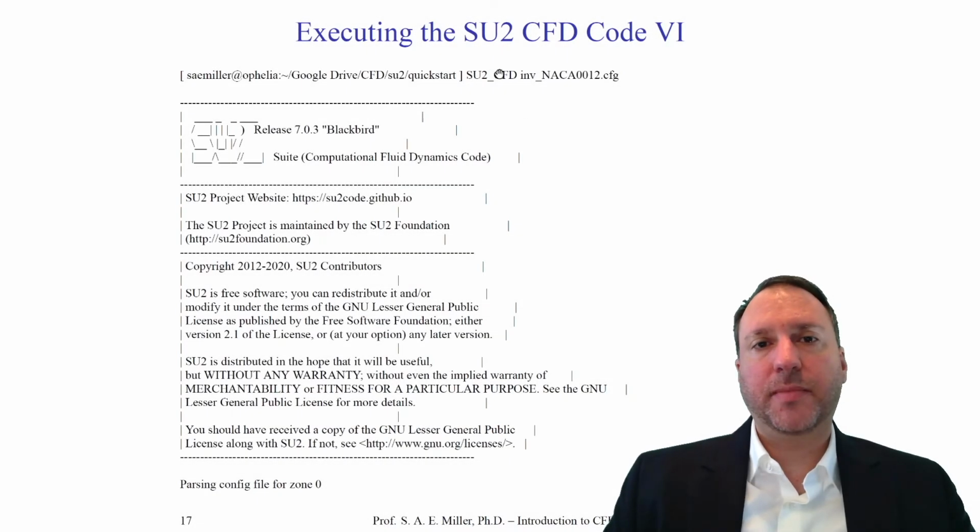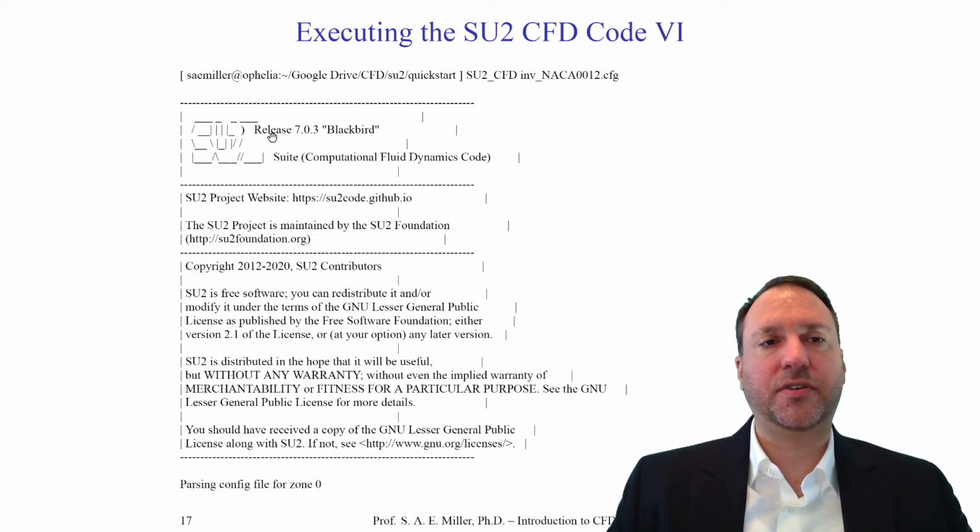Here, I've run the command without my extra information to pipe it to a file. I've executed SU2_CFD inv_NACA0012.cfg. So the first thing that appears whenever you run the solver is just the comments. This is the version of the solver of SU2.